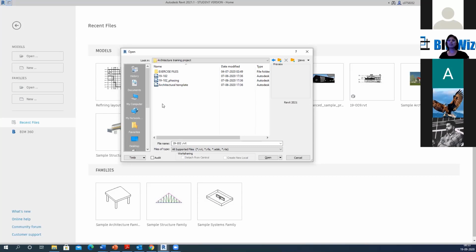It saves your file from corruption. It saves your efforts. If there are any small errors, it fixes the errors itself. So it's a good practice that if you decide to do your thesis in Revit, and there's a lot of changes and back and forth happening, I would say that at least every 3 to 4 days, do consider auditing your file.